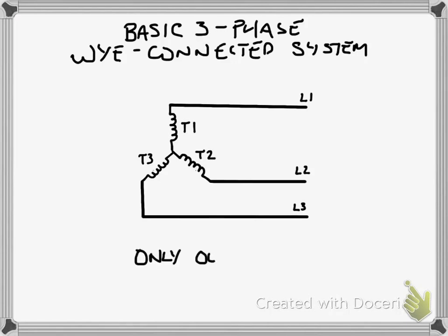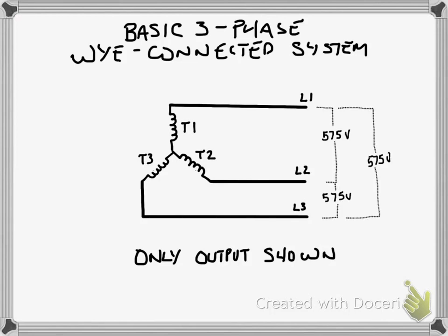Now, we can also look at specifically how those designations might be formed. So we can have three different designations, and in those designations, we're going to look at those two-letter terms that I just described. So we can have a TN, meaning that the source is directly earthed, and on the load or consumption side, the chassis is also directly earthed. We can have a TT system, where both systems have independent chassis grounding. And we can have an IT system, where we have an isolated supply and a separate earth that is bonded at the point of consumption.